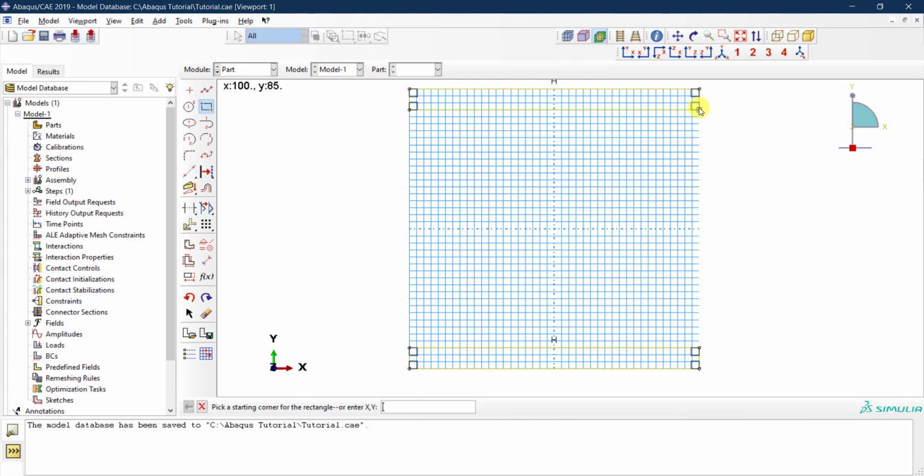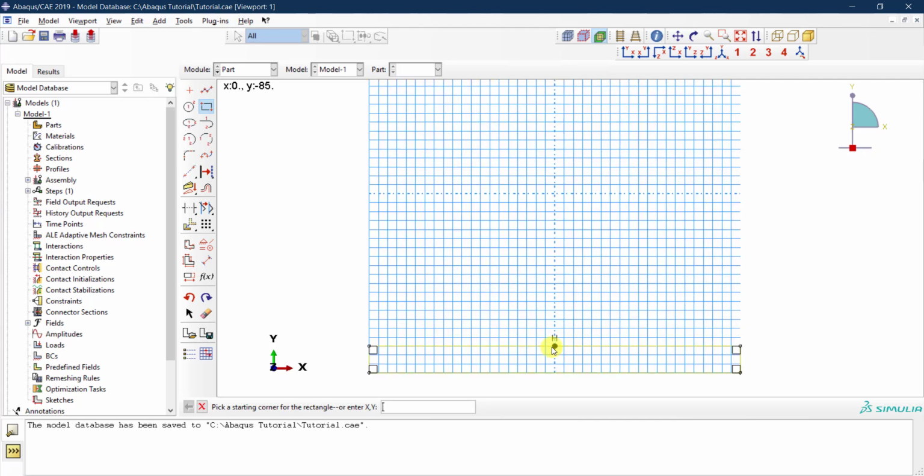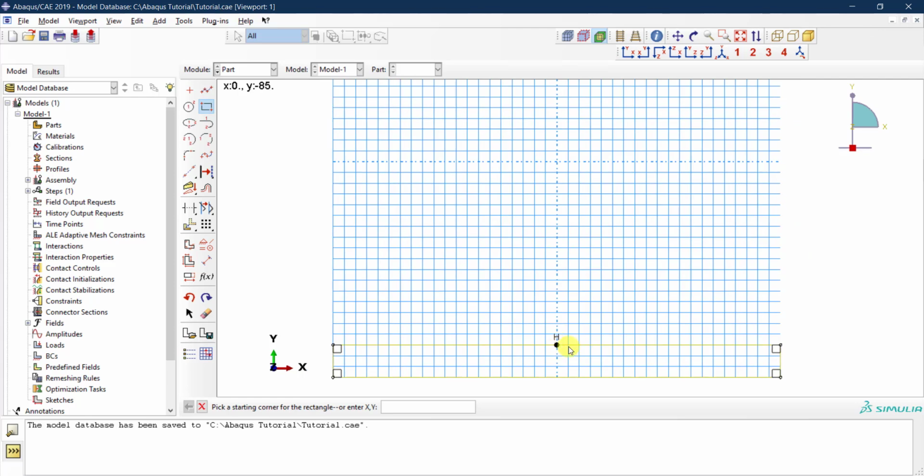As you see here, the rectangle has been drawn automatically. You have these labels, like you see H. If I zoom, it says H. H means that this line has a constraint assigned to it that it's horizontal. You can delete this constraint, but I will leave it. That's fine. But typically you can assign constraints to some lines. And over here, you have the perpendicular label in the corners. Mainly this is a constraint that says that this line is always perpendicular to this one.